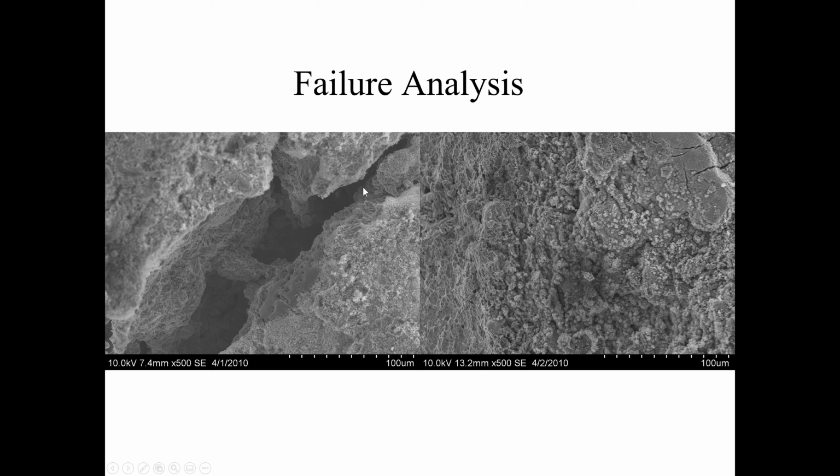It's shiny, it's mirror flat, but under the microscope you can see the internal damage. Normally when steel fails, it bends. This sample just snapped. It looked like somebody made it out of plastic and just twisted it and snapped it. When it hits a certain structural failure point, it just goes.